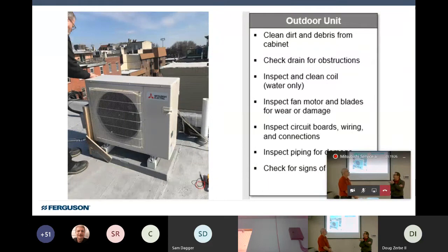before there was UV rated insulation. So I can tell you that I know that there's a lot of black Armaflex that is probably missing on a lot of exposed jobs, roof jobs. And you think about it, on this particular job, you could have 15, 20 feet of exposed line laying across that black hot roof before it goes down to a pitch pocket. Right. And that's kind of the way this was.